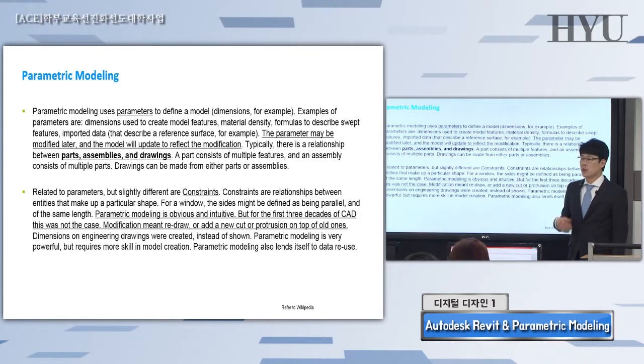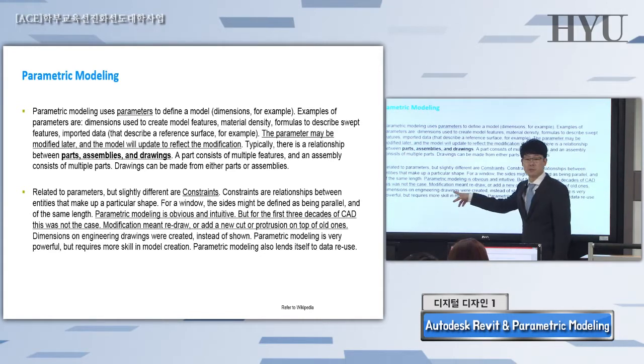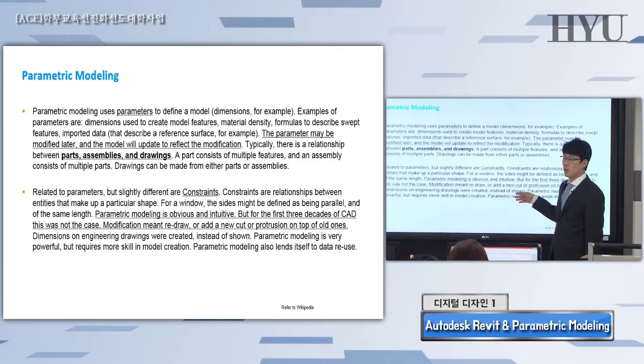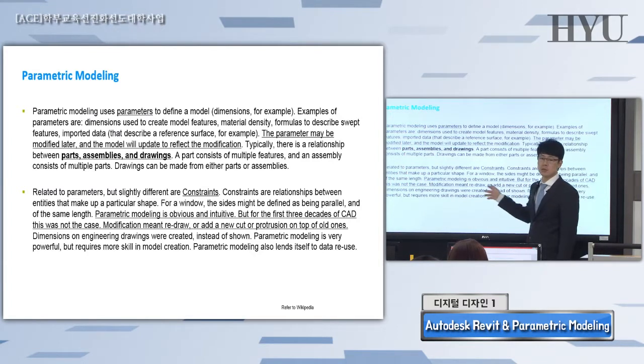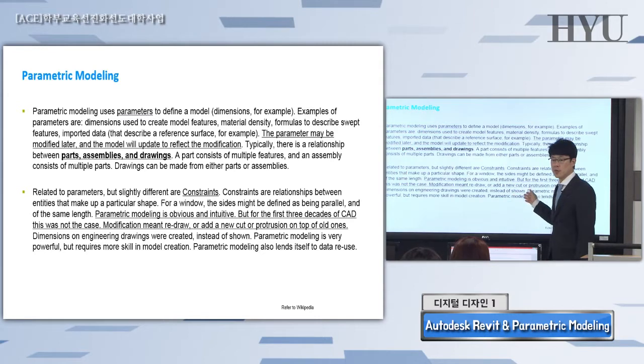For example, in today's lab exercise, we're going to make an entire building. And so far, we have the level 5 model, okay? What if you copy such level 5 objects to level 6? Simply change all objects' constraints from level 5 to level 6.